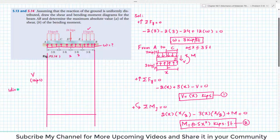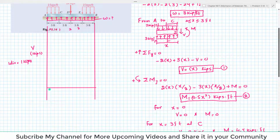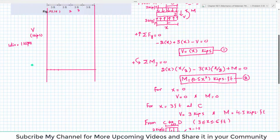Okay. Now you can take here one division is equal to 1 kips. So at x is equal to 0, we know that shear force is equal to 0 and bending moment will be equal to 0. And here 1 division is equal to 1 feet. Clear? So at x is equal to 3, we have V is equal to 3 kips positive. So 1, 2, 3. So it will be like this. So this is 3 kips.